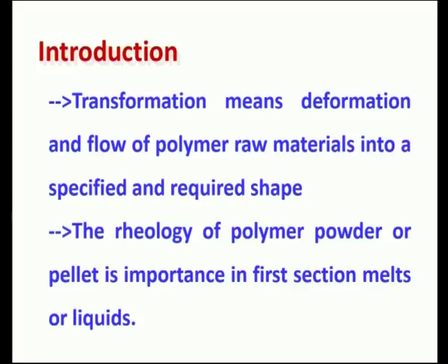The feed zone is where you drop these pellets. Polymeric materials are mostly available in the form of either powder or pellets, and they are fed into the feed zone. The metering zone is where these pellets or powders try to get into a viscous form. So that is where rheology is important, that is the first section of the melt flow.